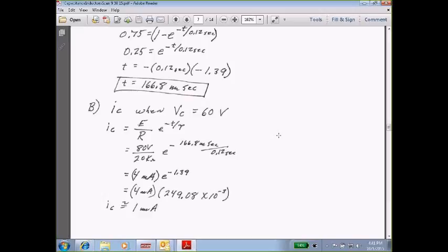Because if the current was going through it, it would have to punch through, in this case, our rubber diaphragm, but in the case of a capacitor, it would have to actually punch through the dielectric material. So that's how I explain to them how we use it in electronics. We call them coupling caps to couple the AC voltage, blocking caps to block the DC voltage, and then things start ringing a bell.